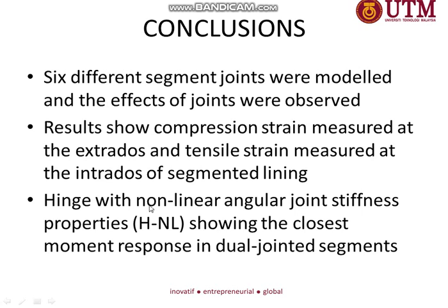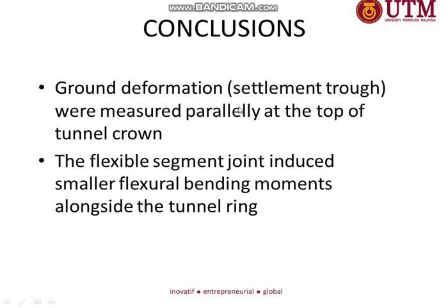Hinge with nonlinear angular joint stiffness properties showed the closest moment response to the dual jointed segment. The longitudinal settlement has been measured, and we can see that a flexible segment joint induces a smaller flexural bending moment and resembles ground settlement better compared to the tie constraint or continuous segment joint model.